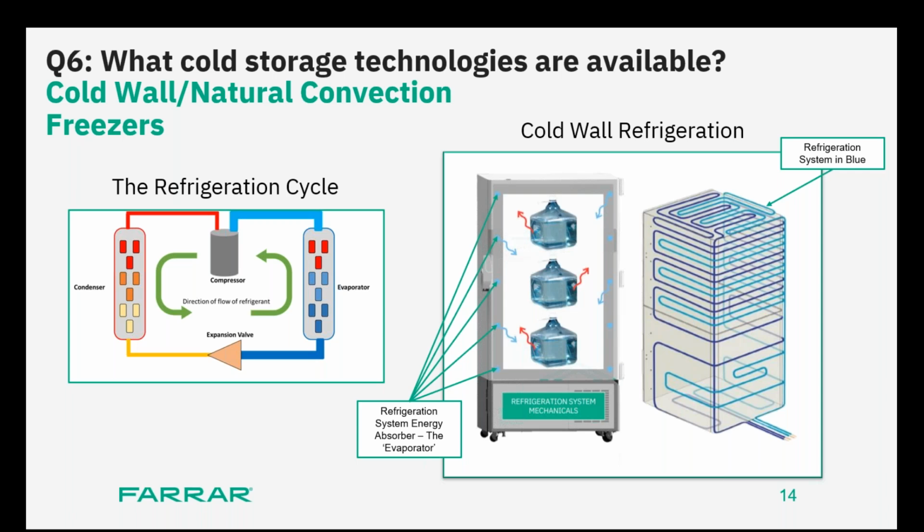Compare that to another scenario where you're working at a research facility, an example that I alluded to previously, where you're opening the door on a regular basis, between 10 and 15 times. You can imagine how warm air is coming in. And if you have moisture in air, it's going to be even worse. So that's when you have to have a process in place that would mitigate that temperature excursion. So for that, you're thinking about another solution, which we will be talking about shortly. And that is known as the forced air convection. So I'll save that until the next segment. So Rebecca, back to you.